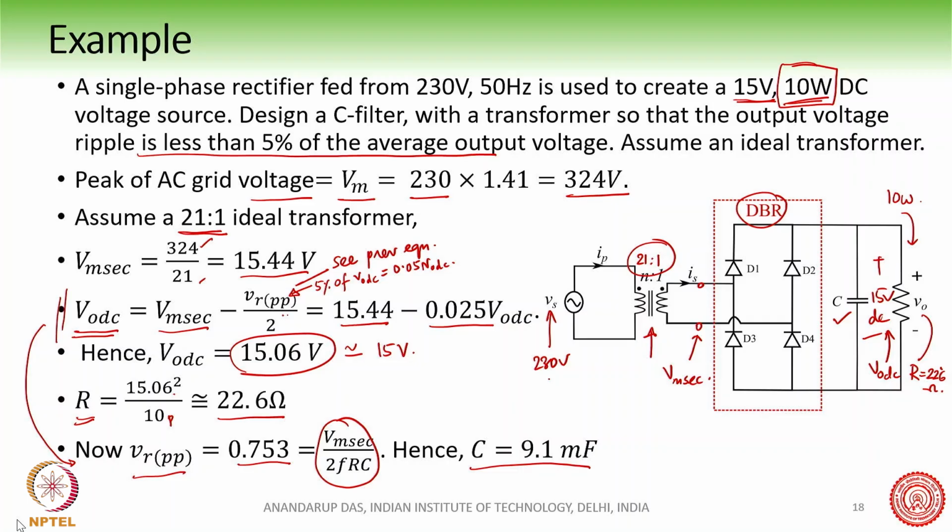The challenge of this approach is that if there is any fluctuation in the input AC voltage, the output voltage is not at all controlled. It is totally uncontrolled. So it's a crude power supply, but it will work. The other problem is that you cannot adjust the output voltage. If there is input voltage fluctuation, you cannot change the output voltage so that a nice stable output voltage is possible.